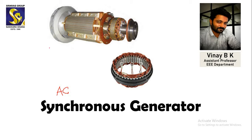And the difference between DC generator and AC generator is in the construction. In a DC machine, as I told, there are two important constructional parts in a machine. One is a stationary part, which we can call the stator. The other is a rotating part, which we can call the rotor. In a DC generator, the stationary part is the field winding, and the rotating part is the armature winding.